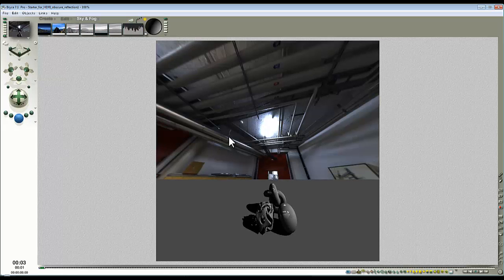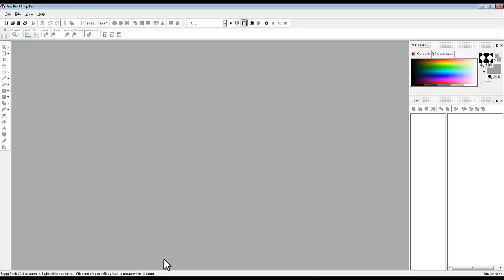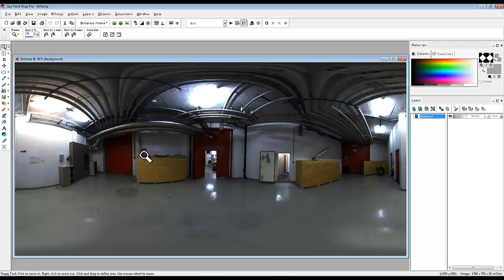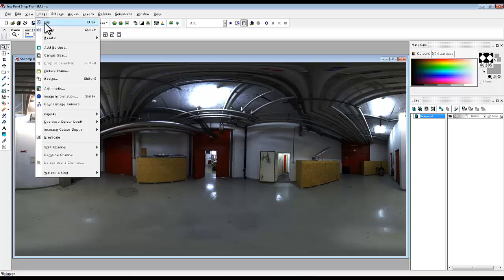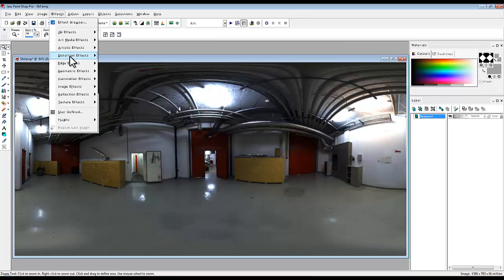Okay, so the orientation's changed. I can probably correct for that actually, if I think about it. I'll just have a, yeah, okay. If you want to do this correction, I'm going to point this out now because this isn't really tutorial, this is explanation. If you want to correct so your export is in the correct orientation, you need to take your exported spherical map, that's that, and then you go image and mirror image. No, it's not image, it's effect.